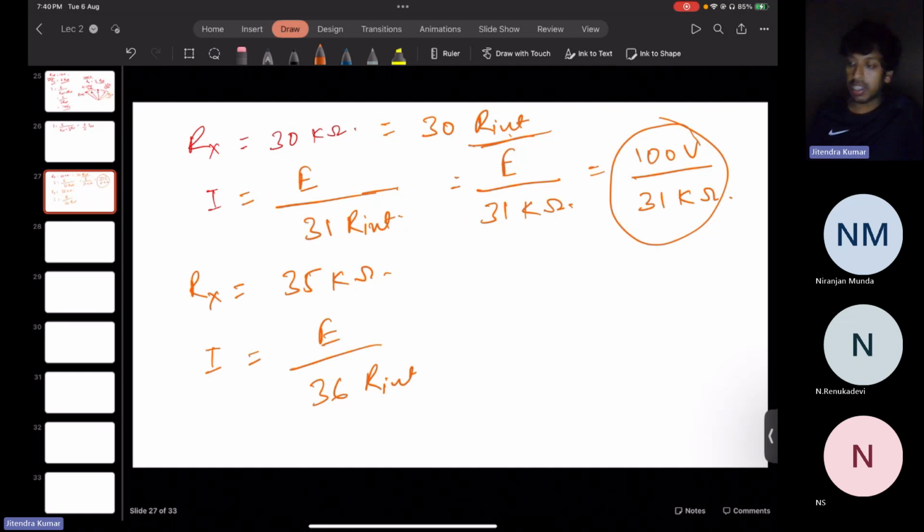So the conclusion is, if external resistance is very significantly higher than your internal resistance, then you are not going to read very easily, or there will be high error in the circuit. So you will not get the exact value of your external resistance. On the other hand, if you have external resistance very close to your internal resistance, your circuit will show you close to accurate reading.